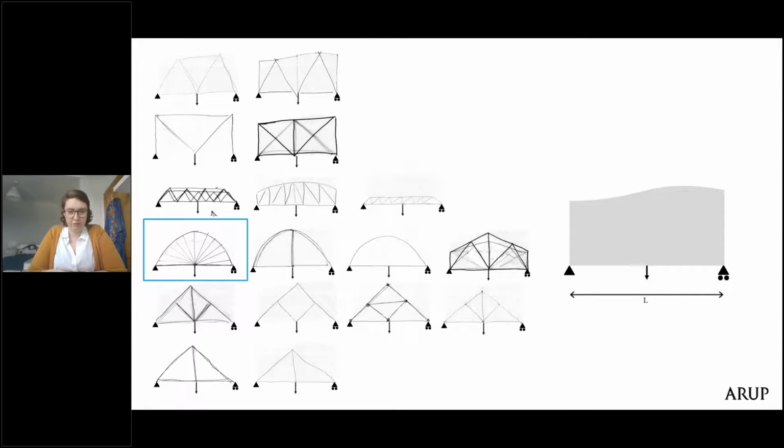And you can see that the intuitive engineering forms might be applying some traditional structures, but the question here is about the absolute minimum volume, and understanding that the solution to absolute minimum volume is this Michell truss, a half bike wheel, and we can then layer on top of that the real-world engineering constraints that enable something to be buildable.